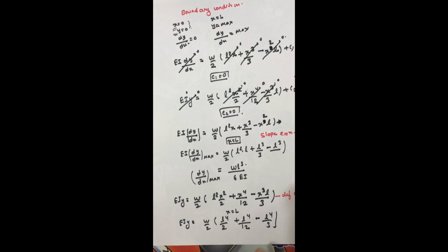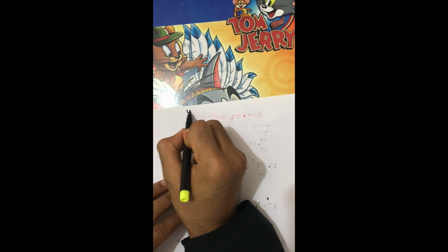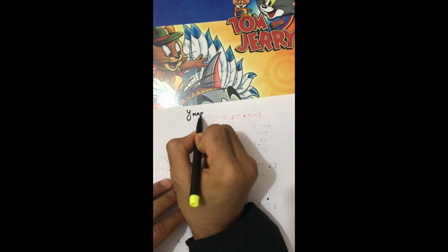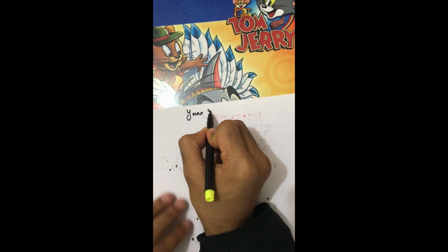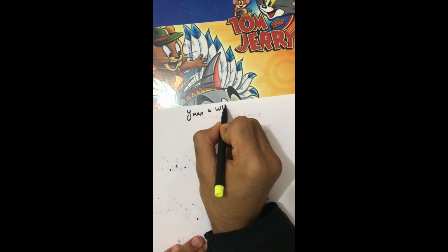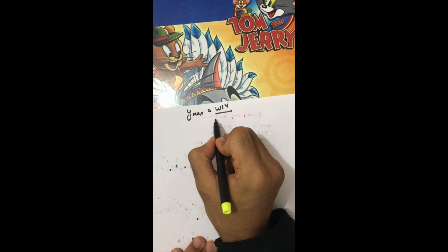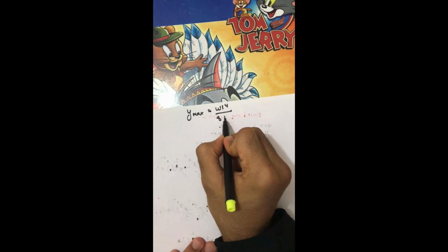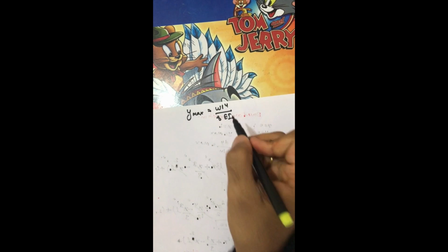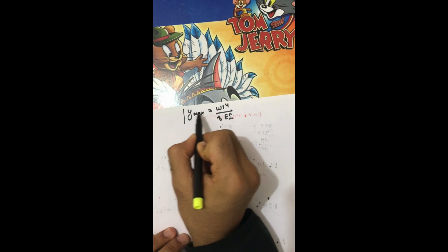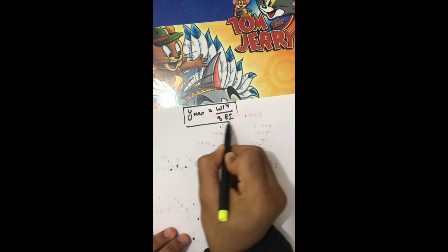Once you solve this, you will get y maximum equals w L to the power of 4 divided by 8 EI. So this is our maximum deflection.